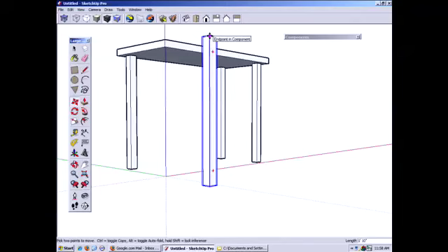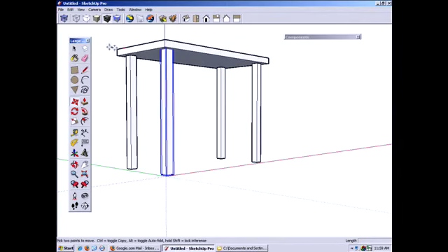The question was how come I moved them to the corners individually and then I could select just one and move it. The key to components is that when you're editing a component, changes happen to all the components, no matter what you're doing. If I select this component and move it, understand that I'm not editing the component. That's the difference. And that's a key thing you're going to have to really dig into this morning: understand when you're editing a component. It's going to become very crucial as we get into component nesting.